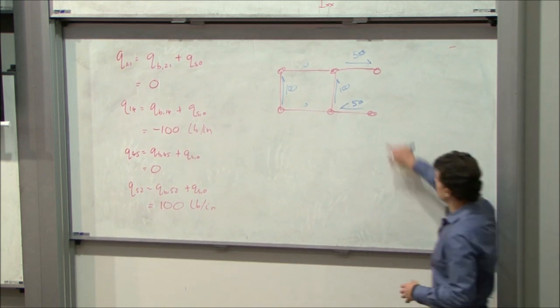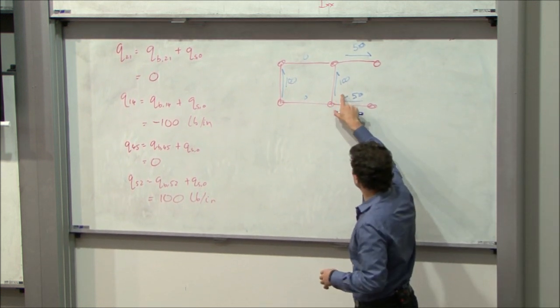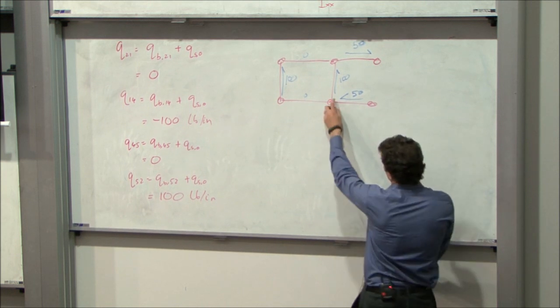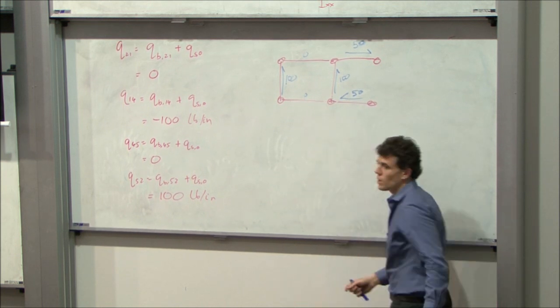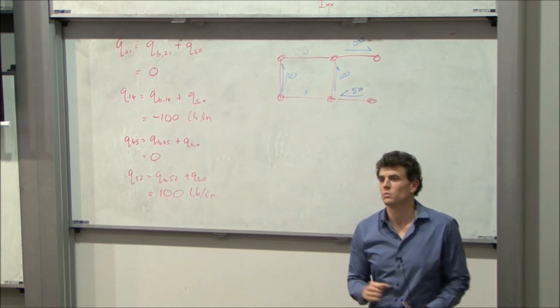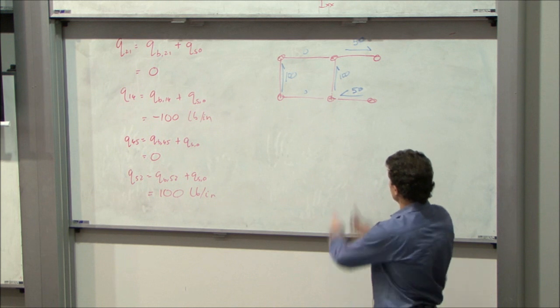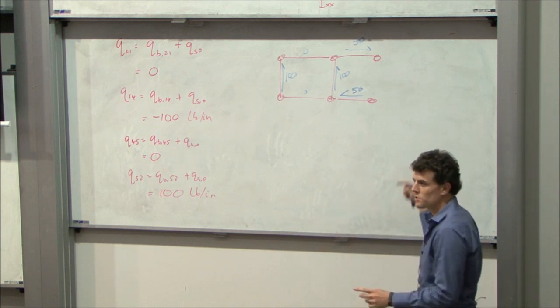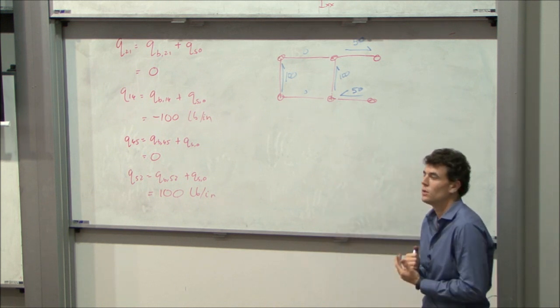So we see that we don't necessarily get the shear flows equaling going in and out of the joint because the boom is carrying some force as well. But the shear flows are all heading in the direction we'd expect them to be heading. Okay, we've applied a vertical shear force, so we expect our shear flows to be generally heading in the vertical direction.